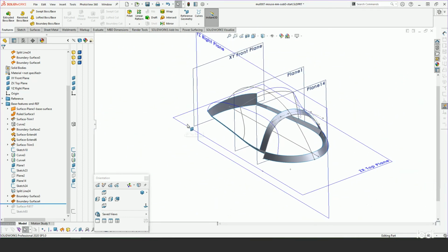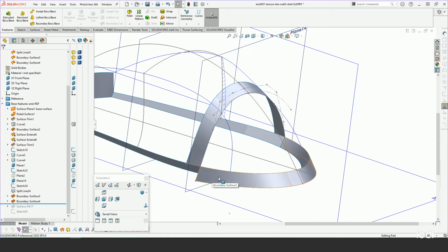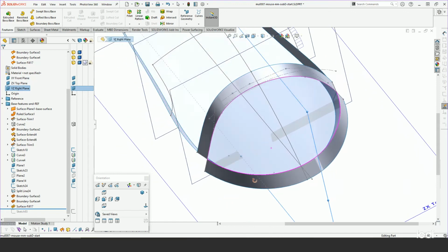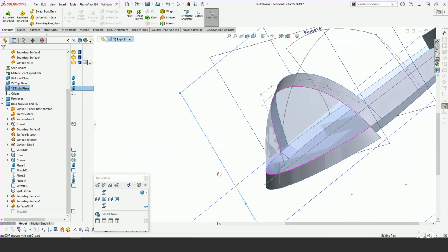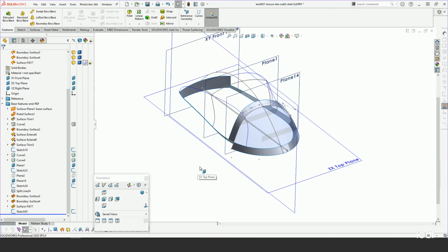And then towards the back, with power surfacing, as is true with some of the other sub-D modelers, you can use surfaces to align the sub-D model to. You can not only align, but you can also make tangent. And so what I do here is I'll actually be using these surfaces to drive the direction of the hard creased edge of the sub-D at this point. And then I have another one in here. I'm not sure I actually ended up using it, but I did a fill surface on this back just to try to get a very continuous example of what that rear cap of the mouse is like. Because the design intent is that where your palm rests on the back of this mouse, it's almost spherical-like and very, very continuous. So those are the reference surfaces that become important.